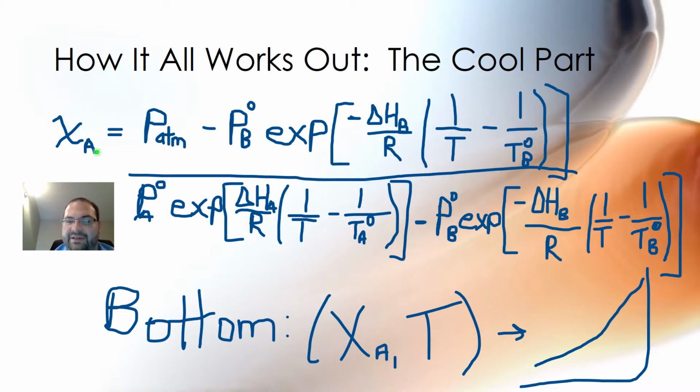That's the mole fraction of the liquid, because you're looking at the vapor pressure for the normal boiling point. When you talk about that, it's all based on the partial pressures there. So it's the total pressure of the system minus the pressure from component B divided by the pressure of component A minus the pressure of component B when they were partial pressures for those compounds.